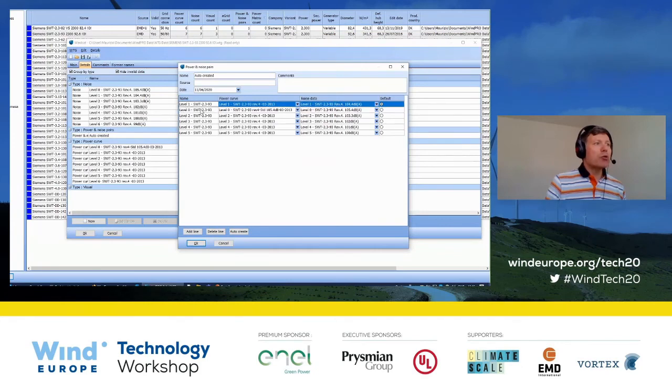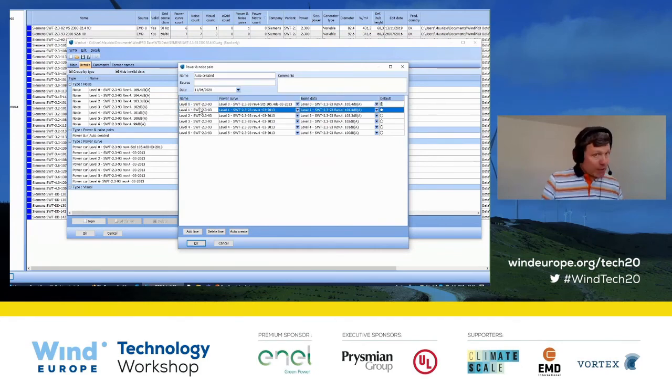One thing you may notice is that, unfortunately, not always does each and every level number correspond to lower and lower noise emission. So it is crucial that you verify that, especially for Vestas machines, I think, which have a few situations where the noise modes do not correspond exactly to the numbering, and it gets more complicated.